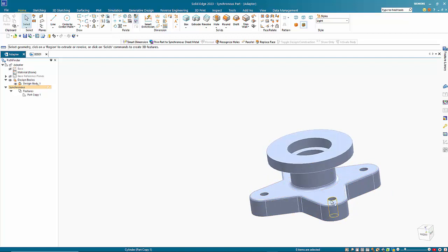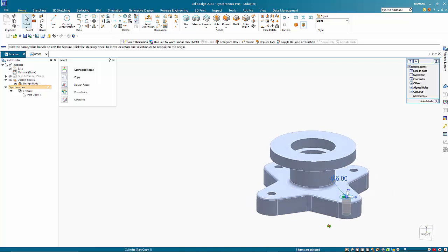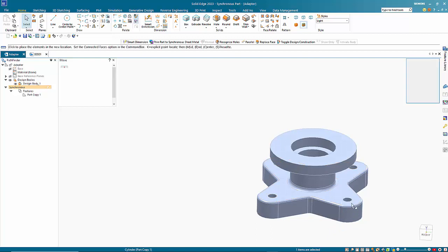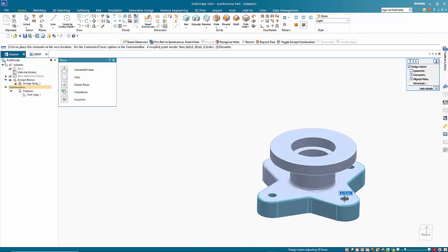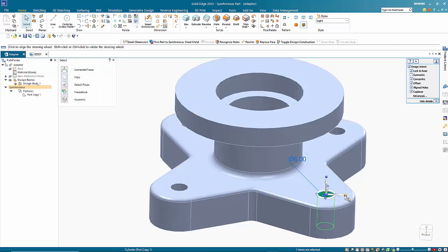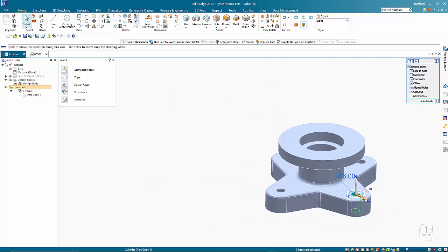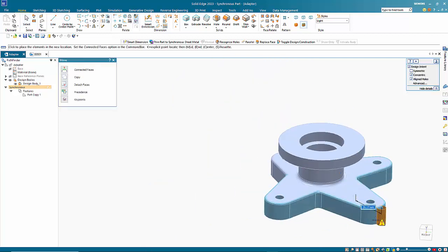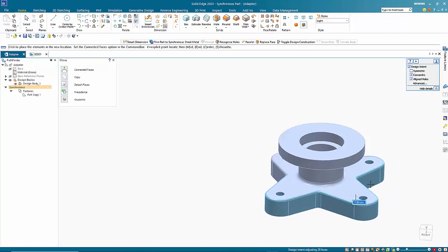Also, for example, I can pick up on a hole such as this one, and clicking on the plane of the steering wheel, we can adjust this in multiple directions. What we might want to do is just reorient the steering wheel using key points and redirecting it so that we can then just pull it out in a single direction, and that allows me to modify that.